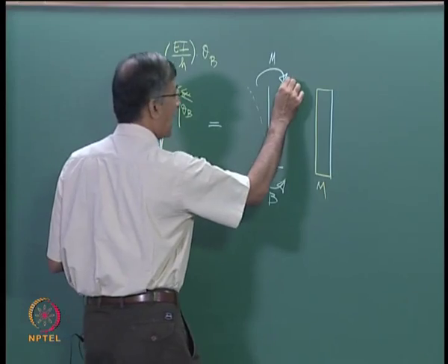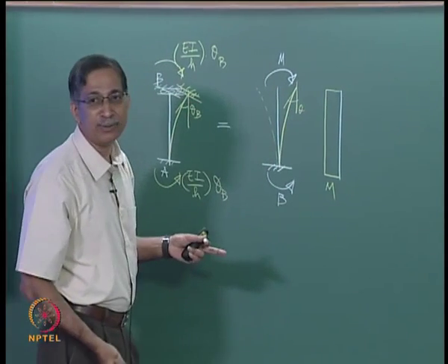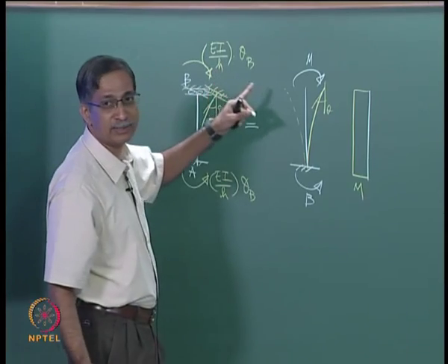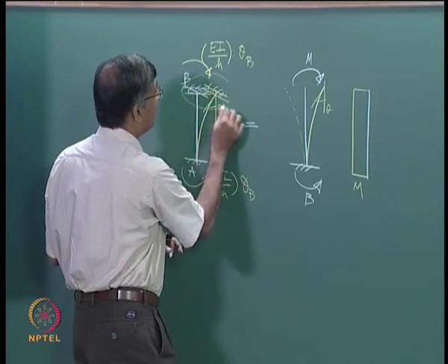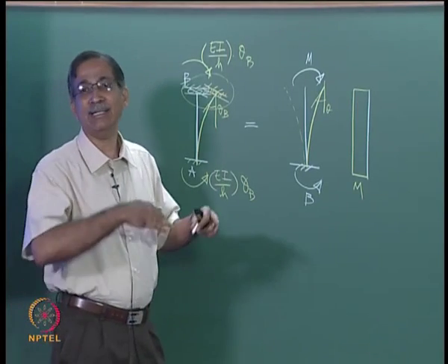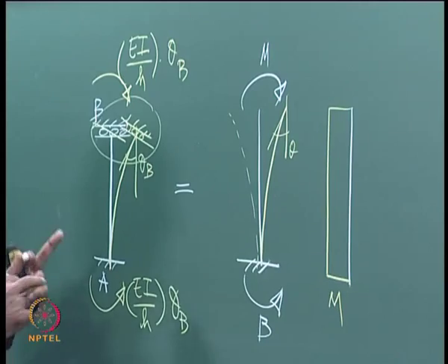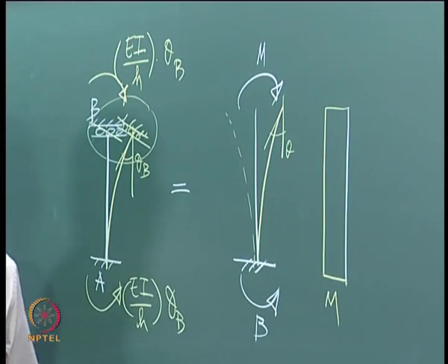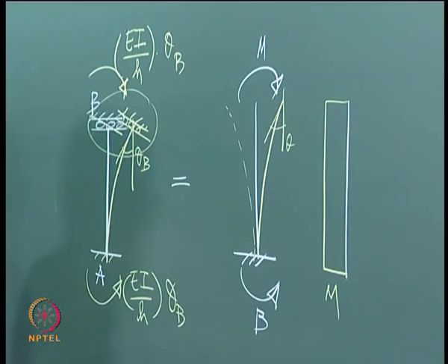And that is why this has to be clockwise. And this is a cantilever, you can use conjugate beam method and show the relationship. So you shouldn't get disturbed by the fact that you can assume it to be rotationally fixed and then release it. So the deflected shape gives you the clue. The behavior is exactly the same. That's the modification you need to do. Clear?